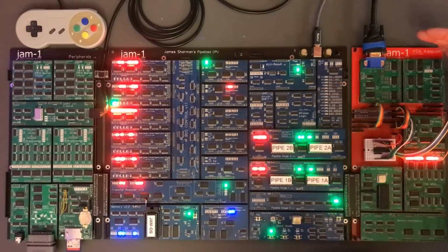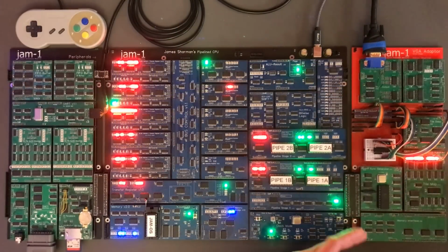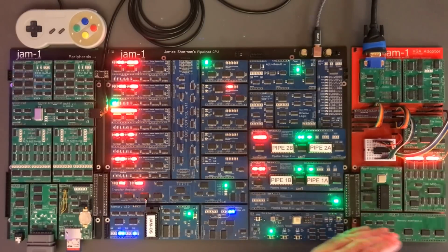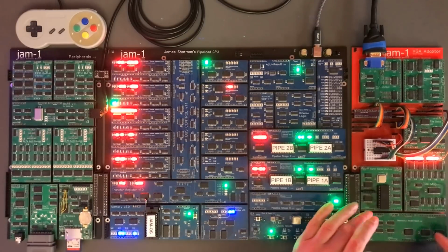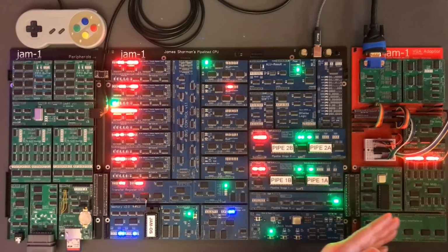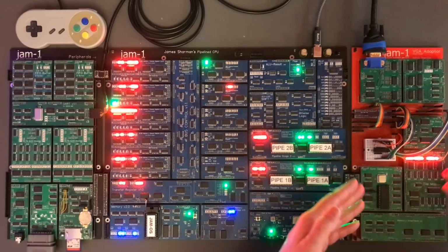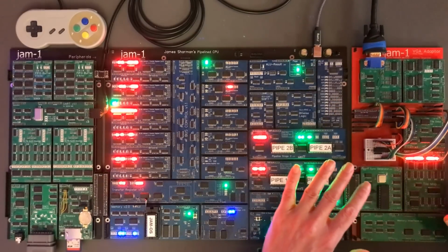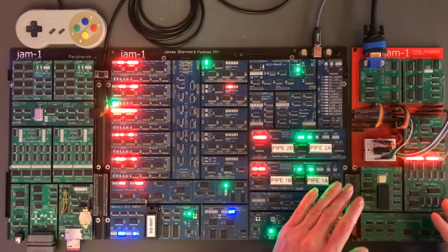So I want to talk about the VGA side of things today, where I've got a problem. Now the memory interface has a very low component density because I deliberately left some space just in case I wanted some stretch goal functionality in there, which to be honest, that's not going to happen. I've got the palette, tile map, tile data, sync generation and the output circuit, and that's the kind of functional display system that lets me do the cube demo and a bunch of other graphical things.